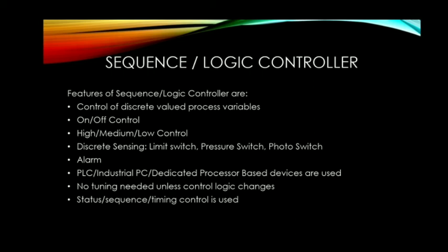In the control of a conveyor system, analog motor control is not applied. Simple on-off control is adequate. Therefore, for this application, the motor starter actuation system may be considered as discrete, having 3 modes, namely, start, stop and run. A modern controller device used extensively for sequence control today in transfer lines, robotics, process control, and many other automated systems is the programmable logic controller, PLC.